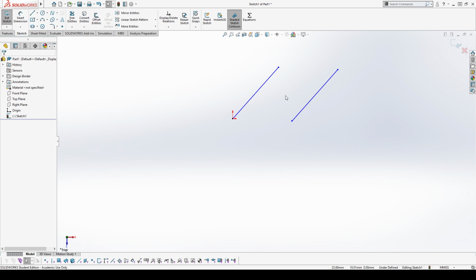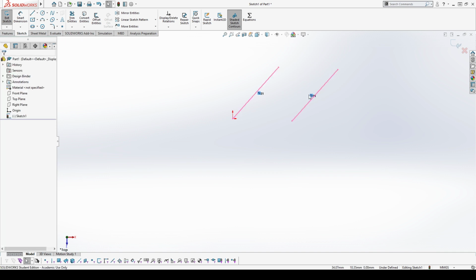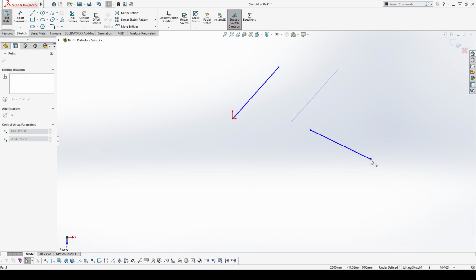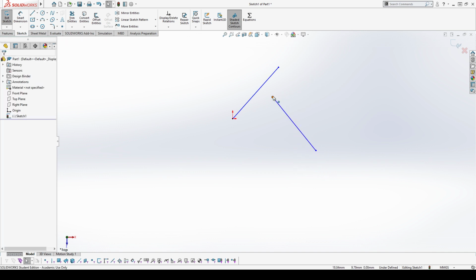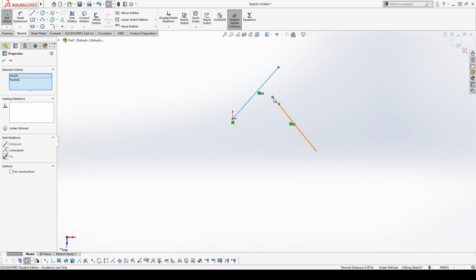We also have a couple options for point-to-line dimensions. So this line here is parallel. I'm going to get rid of that dimension here just so I can kind of show you a few things. Rotate that line around. Cool. So point-to-line. If I click on those two, so that point, the end point of this line, and this line here, I have a couple options.